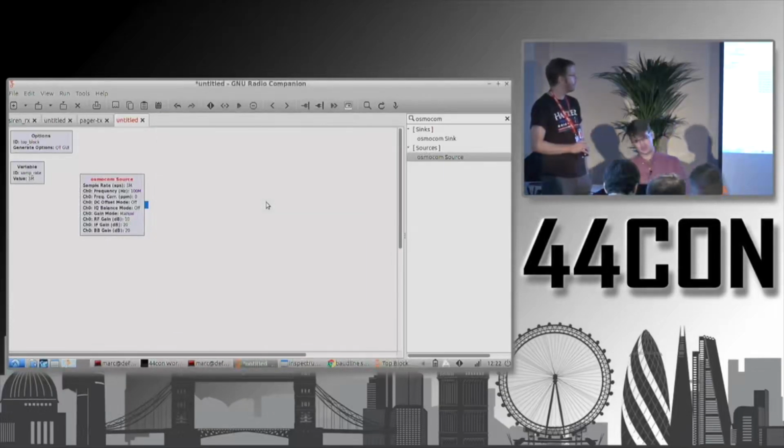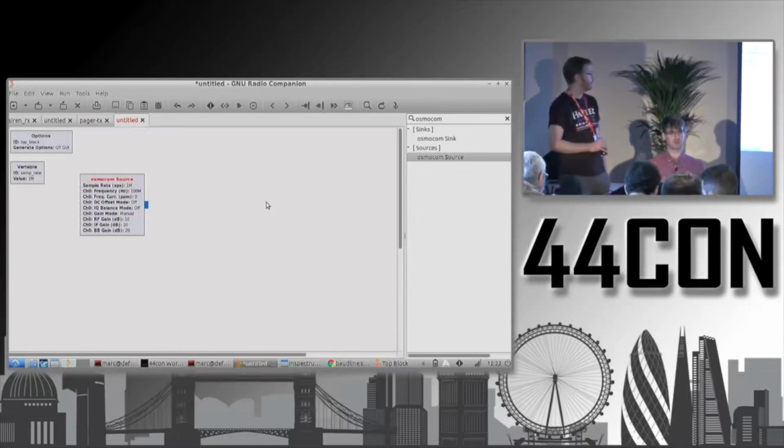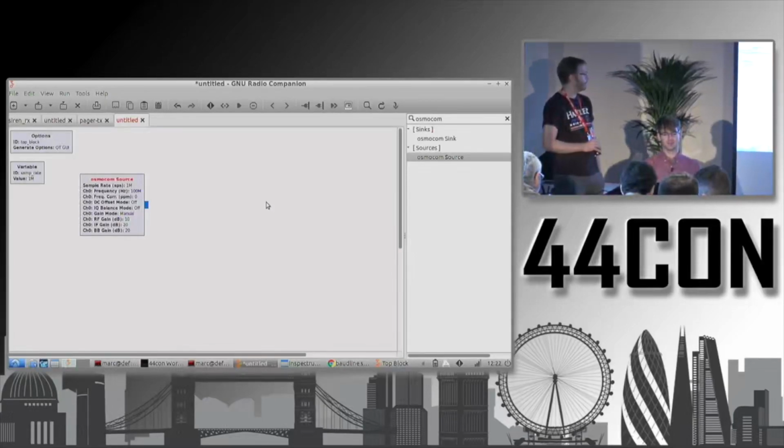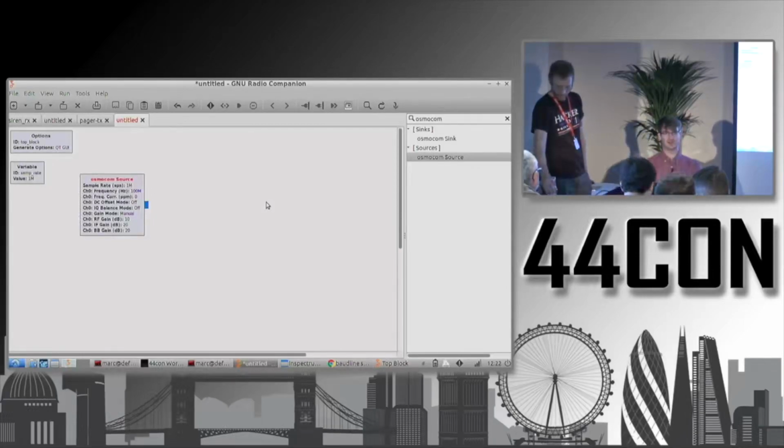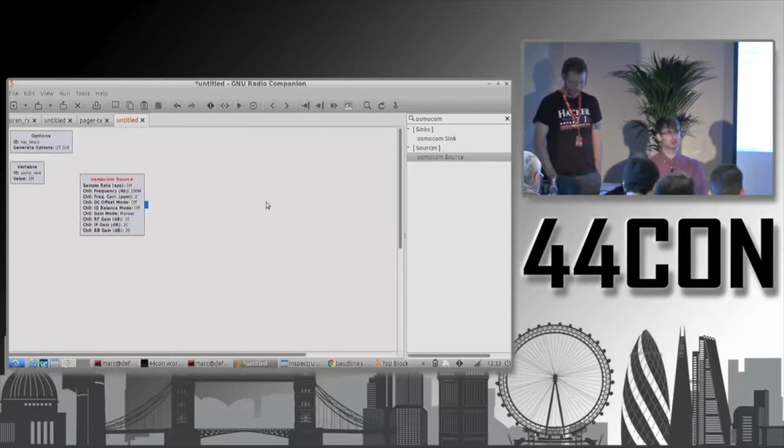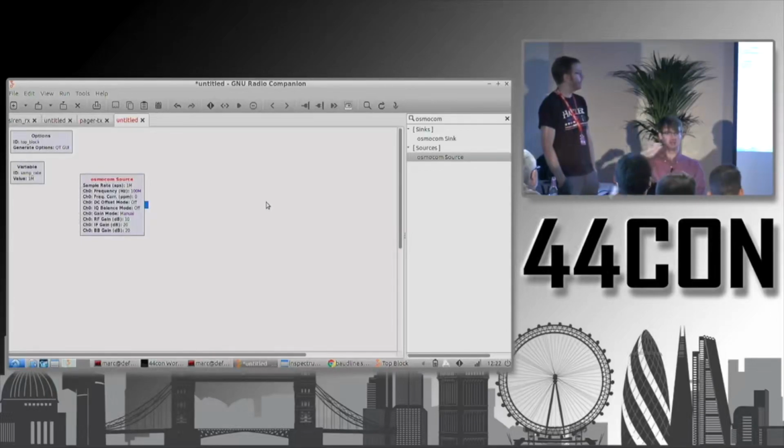And you don't have to be super precise about this. The key thing is that you want to make sure that you're sampling at a fast enough rate to give yourself enough margin with the data rate, with the signal that you're observing. This gets into some of the mathier bits, but basically within communications theory, you have to be sampling at a certain margin above the symbol rate that you're observing. So with software-defined radio and modern tools, just set your sample rate high when you're getting started, and then you can always reduce it later. The only thing it's going to cost you is performance, basically.